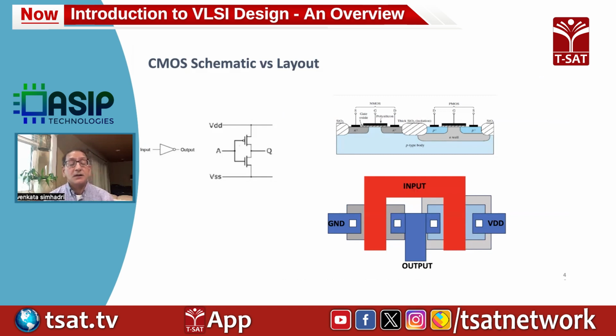So basically, you start with a logic gate, for example an inverter, and how it looks in schematic form. It has a PMOS and NMOS transistor in there. And then how the physical cross-section of the CMOS inverter looks on a wafer.